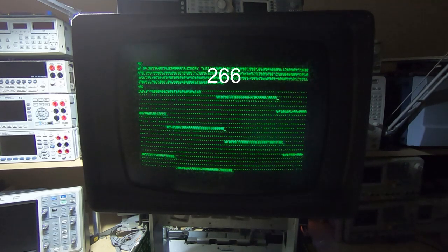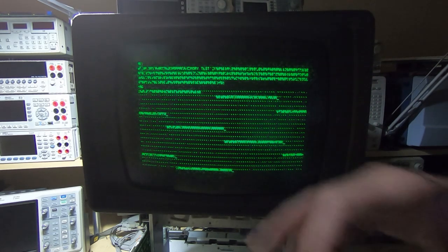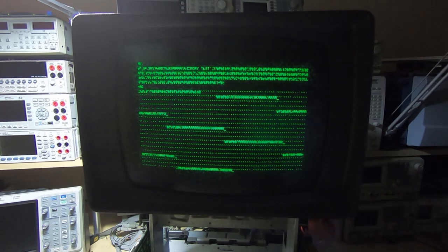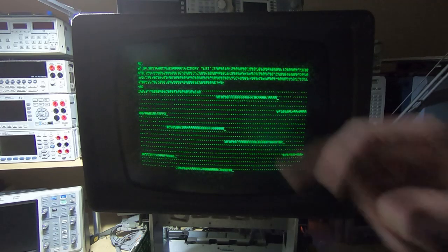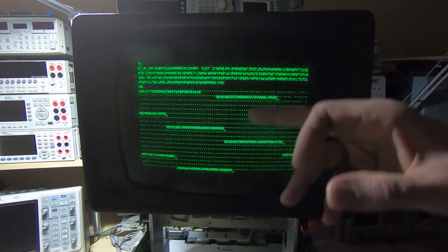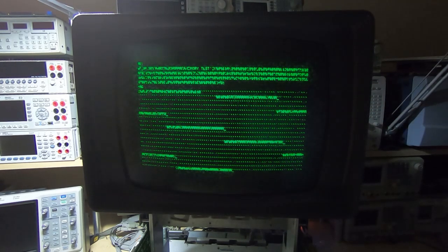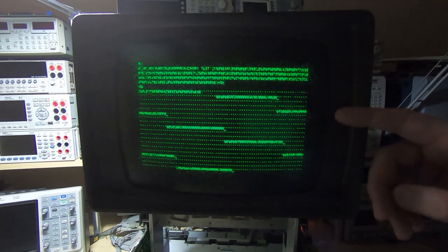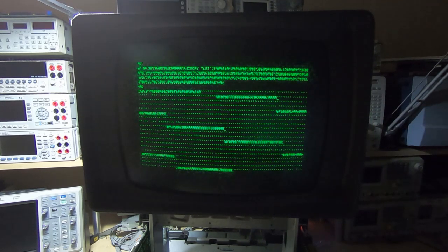I was expecting something that was a multiple of 2, simply because this is normally caused by 1 or more stuck bits, and so you'll get a fairly well defined number sequence when you encounter that. The number of characters in these blocks doesn't make a lot of sense if it's a stuck bit in one of the address counters. So what I'm going to do is turn this off and just briefly explain how the circuit works, and then we'll start trying to figure out what's going on.